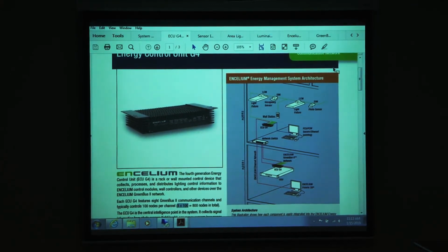And I believe each port is capable of handling, I'm thinking 750 milliamps, I'm not sure. So it splits it. 1.5 amps, I believe, is the rating for this device, split between channels. Depending on how much you're pulling, that will determine the number of devices per channel. So if you have high current draw sensors, that number will be smaller. The less current the sensor draws, the more you can get on that channel.